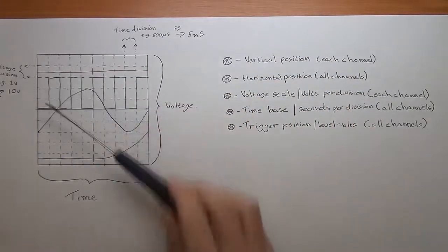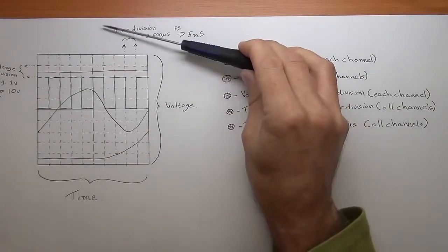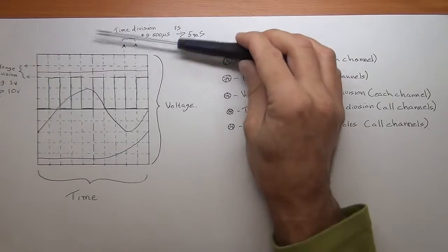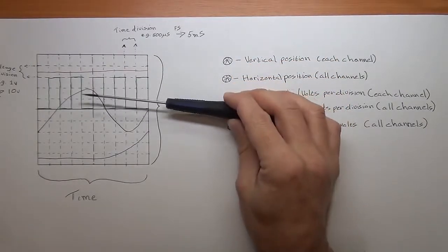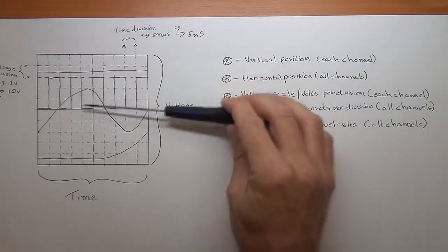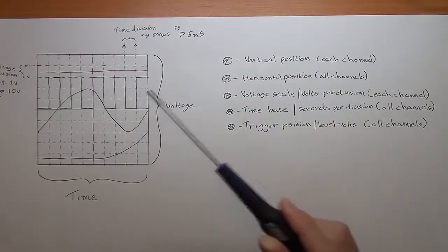Because depending on what scale you've set for your oscilloscope, it might be out of range of the display. As you saw, I had that signal from that battery and I had to pull it down so it was in range of the display and of the measurement values which were pre-selected so that I could see it. And that's the vertical position knob. Very, very simple to use.